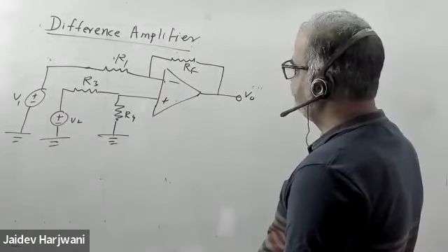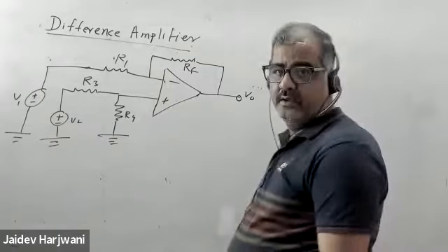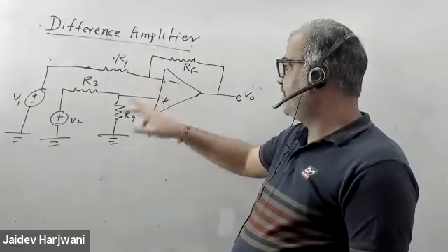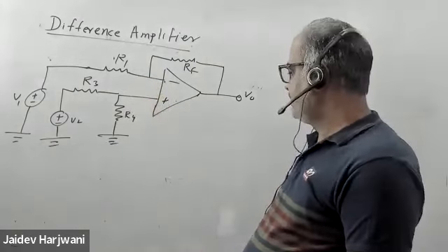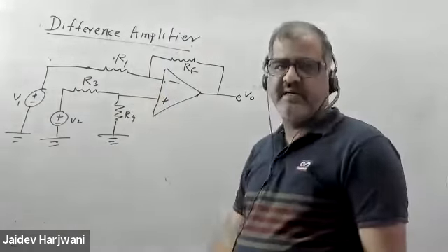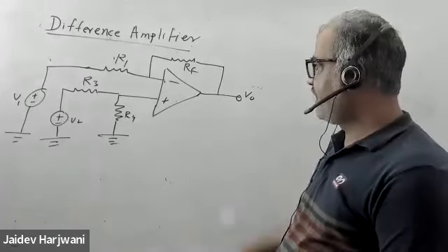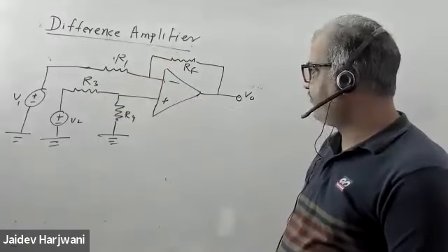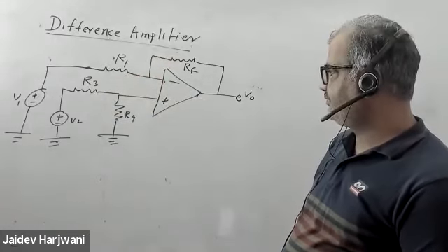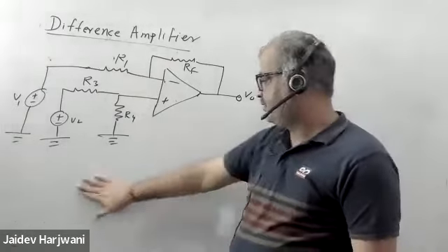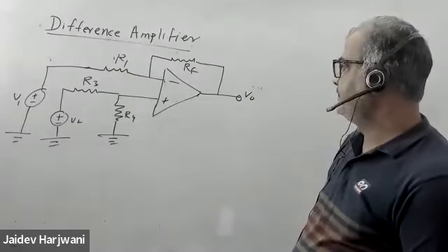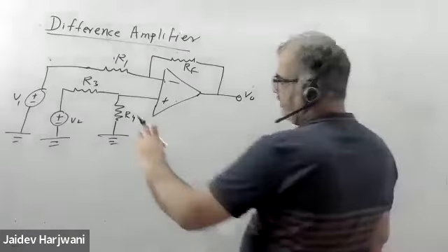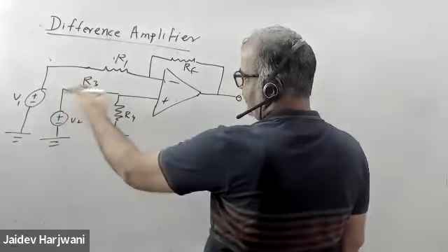So now in this question, you have voltage at the inverting terminal and you also have voltage at the non-inverting terminal. So it is better to apply the superposition principle and calculate V0, or you find the voltage here. What is the voltage here? And then you can do the same as we have been doing, applying current. Okay, so let me do this problem. If you want, you can find the voltage here. Finding the voltage is very easy here.